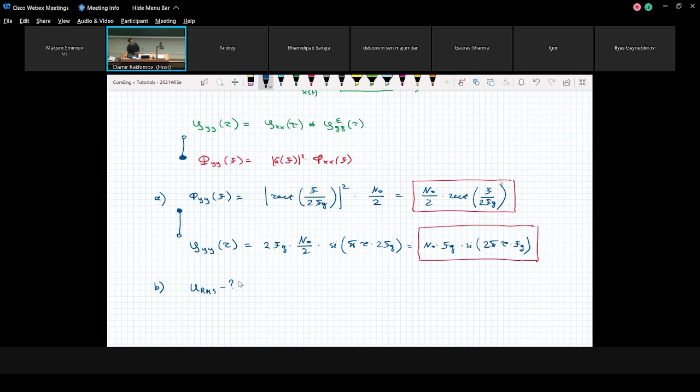I would say you can definitely get RMS without DC. If you don't have any DC component, you can calculate a non-zero RMS. It is the root of the variance. This is the standard deviation, directly related to standard deviation. It tells you, on average, what the fluctuation of your signal is.